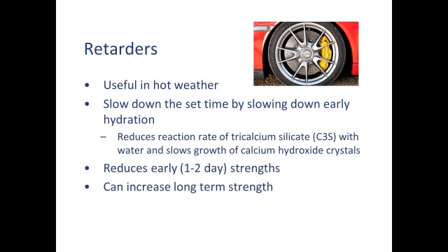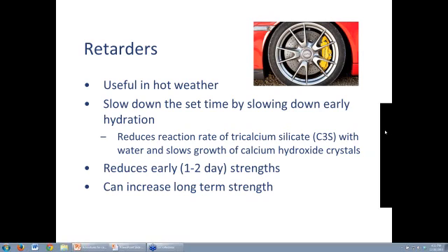Now, the opposite of an accelerator on your car is your brakes. So retarders are ways to slow down your concrete. And I think the best conditions to make concrete in, this is my preferred way, I like the environment I'm in to be hot, and I want to make my concrete cold. The opposite, having a cold environment and having to make my concrete hot, takes a lot of effort. It's very easy, and in my opinion much more pleasant, to be in a warm environment but to work with cold concrete, because cold concrete reacts slower, just the opposite of hot concrete.